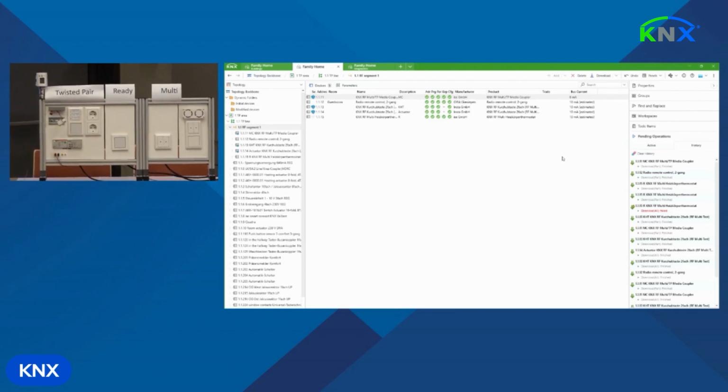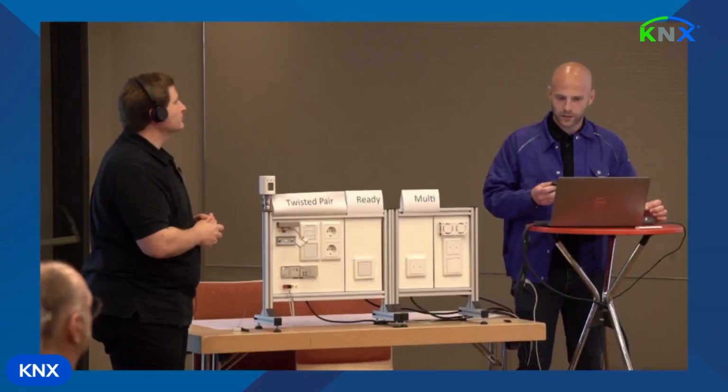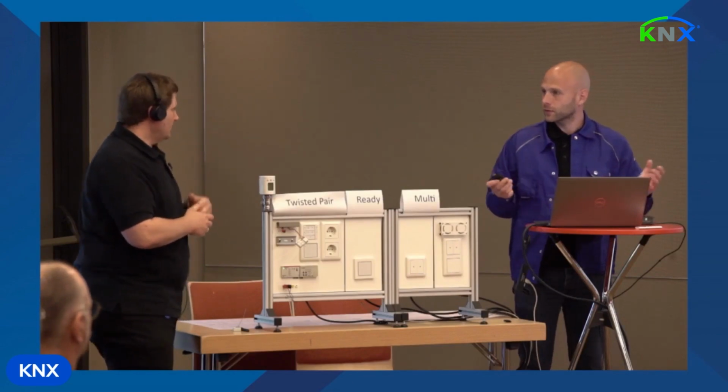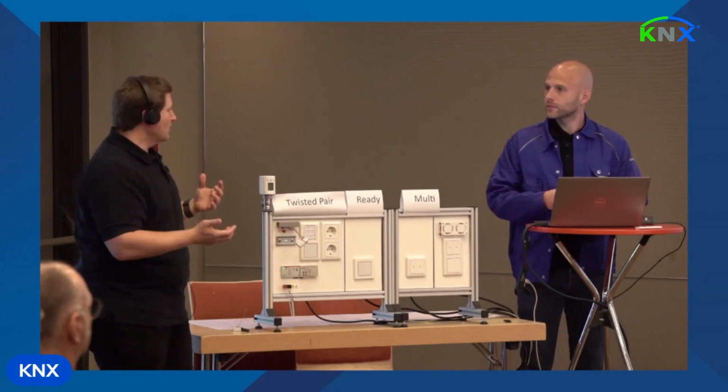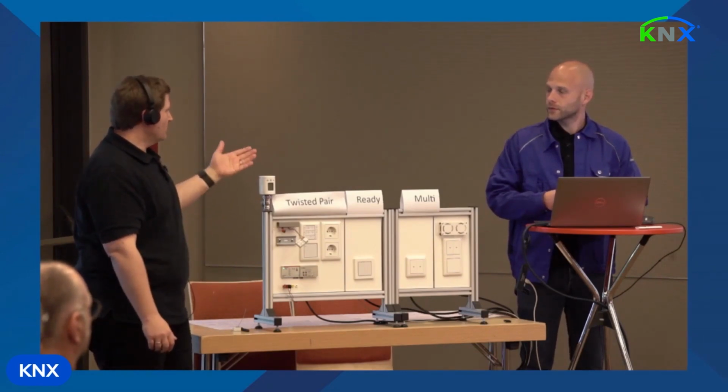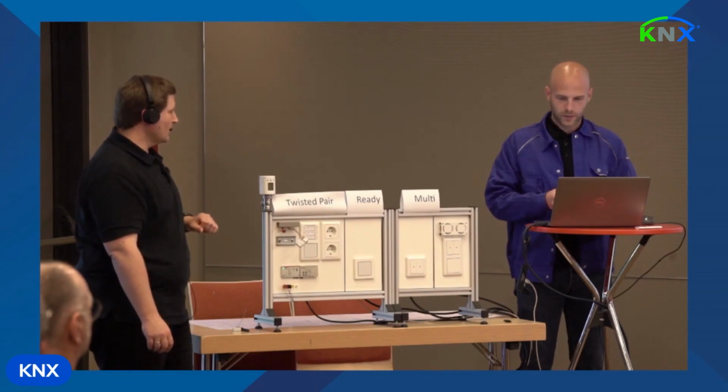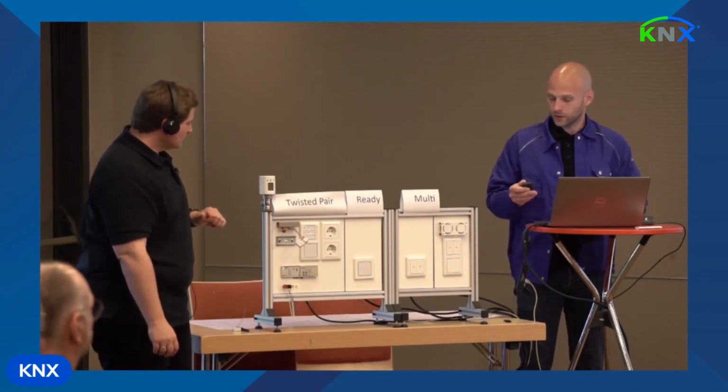But here, again, the media coupler comes in. So he's doing all this magic of supporting SLE, segment coupling, security proxy, and he stands in for this ready device and resends the frame in SLE. So until I programmed also the coupler now, it did not let through the group address. That simply was the issue. The radio, the remote control has sent a ready frame that simply was overheard by the SLE device. Okay, but now that I programmed it, I can try.